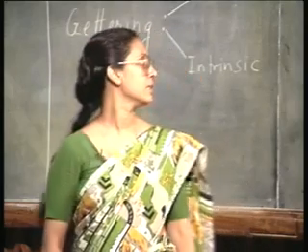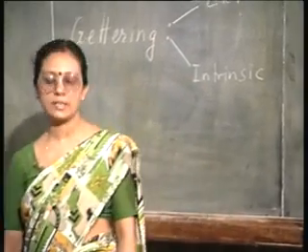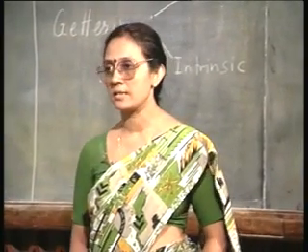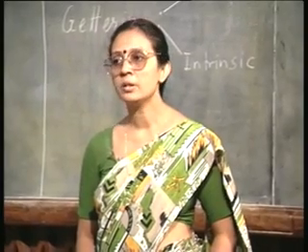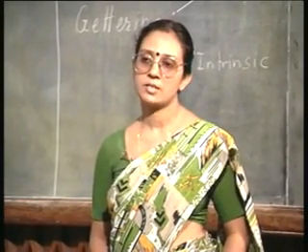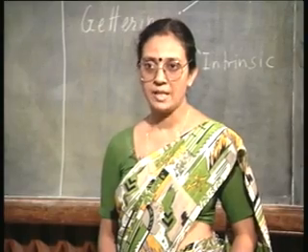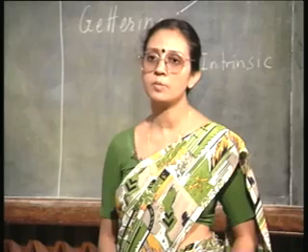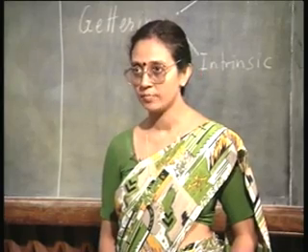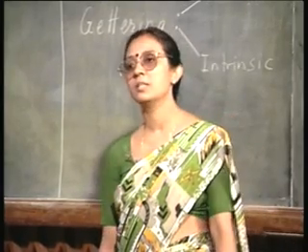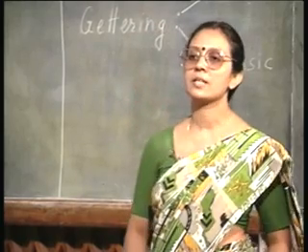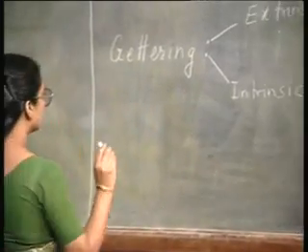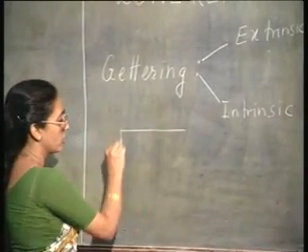The other type of gettering, which is called intrinsic gettering, uses the oxygen that is in the crystal. We told you that if the oxygen is above a certain range, then it will give rise to precipitates, and the precipitates are usually undesirable because dislocations will emanate from them. But you can use it to your advantage, provided you make sure that such precipitates are not there in the active region. Okay. That is what I am trying to say: suppose this is your wafer cross section.